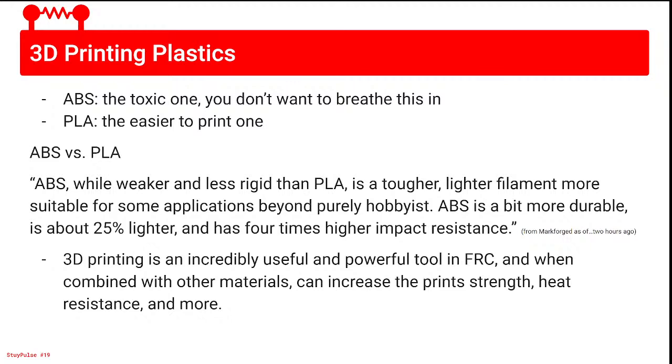PLA is the more common one. It's the one that's safe to use and everyone has it. But something that I quoted from Markforged as of 2 hours ago because I got lazy: ABS, while weaker and less rigid than PLA, is a tougher, lighter filament more suitable for some applications beyond purely hobbyists. ABS is a bit more durable, is about 25% lighter, and has 4 times higher impact resistance.